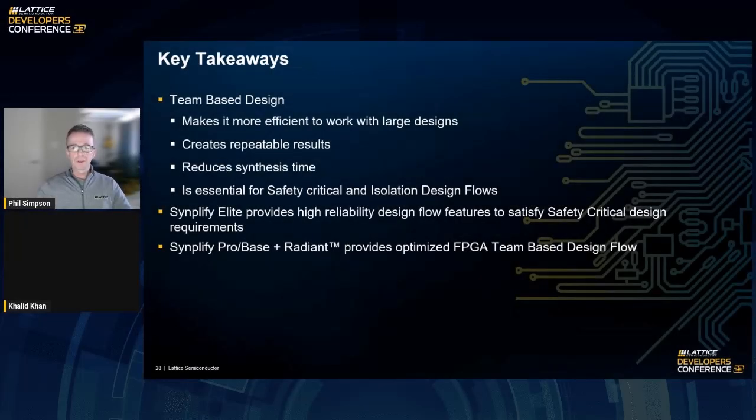So the first question that's come in is regarding the floor planning in the team-based environment. It says, is it recommended to floor plan all of the blocks in the design? So you can floor plan all of the blocks in the design. However, we really recommend that you only floor plan what you really need to floor plan. So in the case of an isolation design flow or safety critical, that would be the portion of the design that you would have to floor plan.